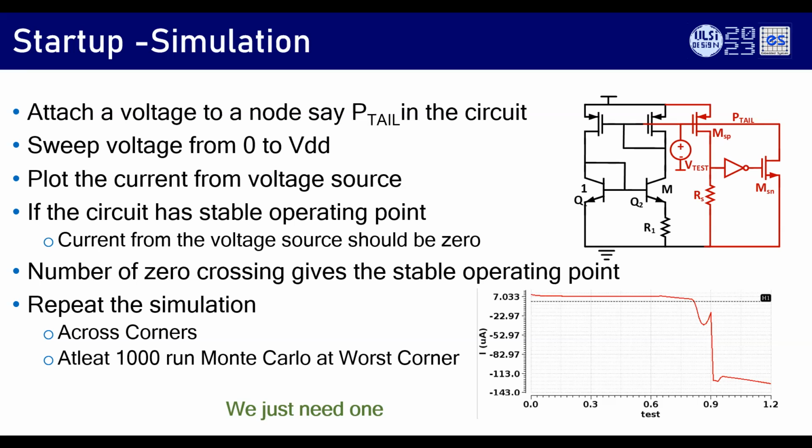It can be. So when I design the bandgap, I also have a test port to disable the startup. For example, in this case, I will just connect the NMOS gate to 0 when I want to disable the startup, just for checking those conditions. Let's say when the chip comes back, it starts oscillating or something like that. I will take that NMOS gate and put it to 0 forcefully to see what happens. If you have that, it's easier.